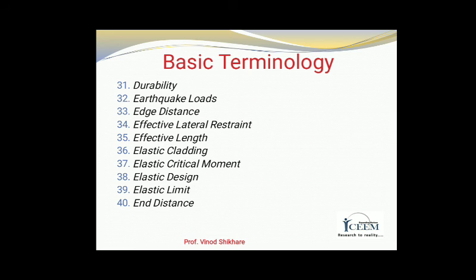And next term is end distance. Distance from the center of a fastener hole or rivet hole to the edge of an element measured parallel to the direction of load transfer is known as end distance.